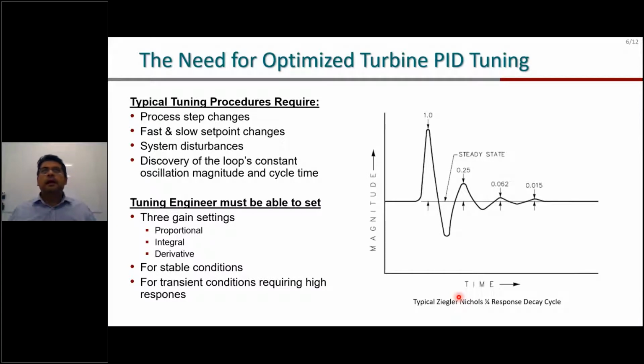So in reality, the tuning of the PID requires a lot of experience, a lot of understanding about the typical response time of the turbine, and an understanding of the system gains, like what the gains are within the system that you are trying to control. It requires understanding of the process itself.